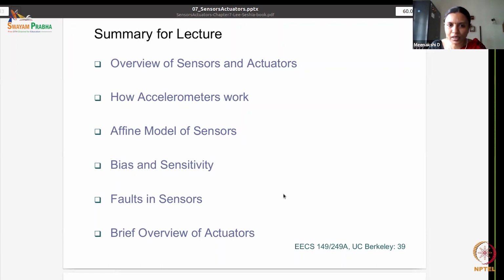And then you start looking at the diagram and how to turn on the LED, what you should do, and stuff like that. For example, when I turn on the LED, assume that my GPIO pins can sink up to 18 milliamps. Assume the LED, when forward biased and turned on, has a voltage drop of 2 volts. Which resistor should you use? That's the kind of decision that you take to be able to work with your actuators and your sensors.